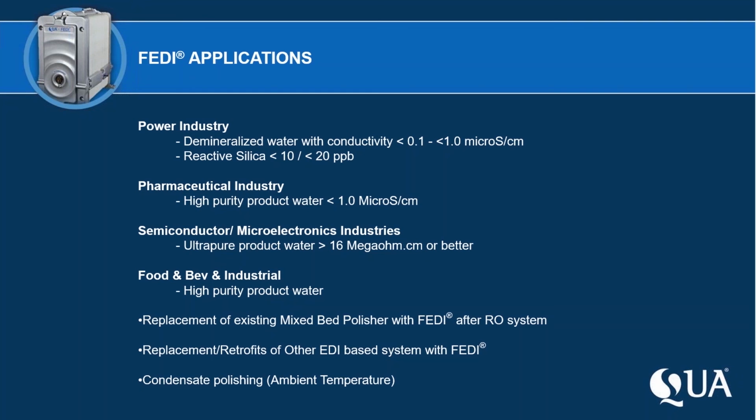So the semiconductor industry doesn't want anything they can measure in the water. They actually set standards for the roadmap for instrumentation companies, where in my early days, PPMs were great. They went to PPBs, parts per billion, evolved into parts per trillion. And today the semiconductor industry is looking for parts per quadrillion. And they give these guidelines to the instrument companies to develop instruments to measure it. They know it's coming, and so they set this roadmap for futuristic measurement for instruments in the industry.